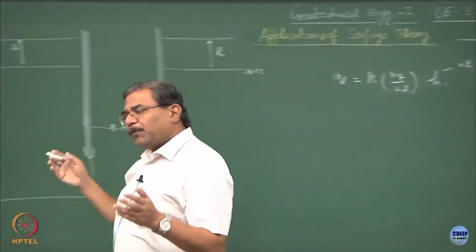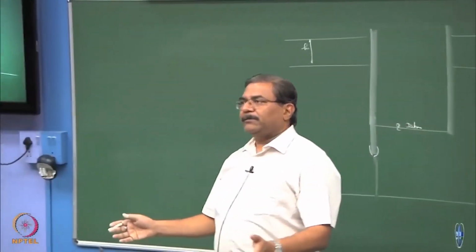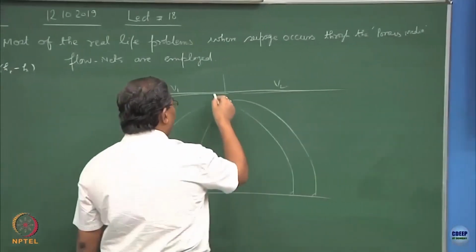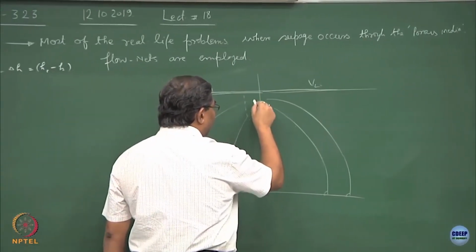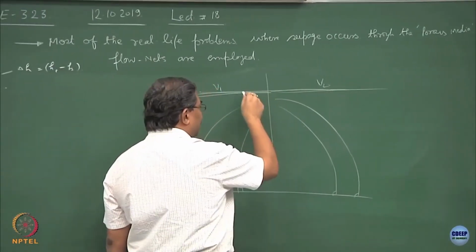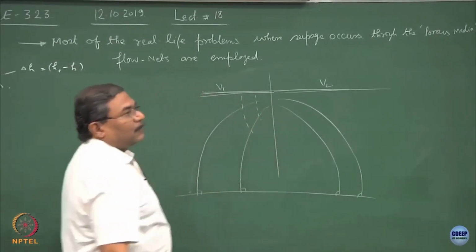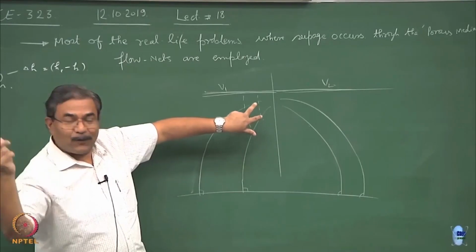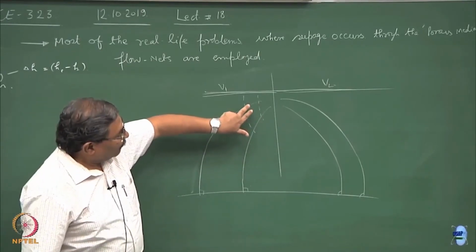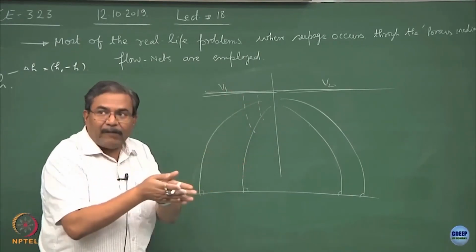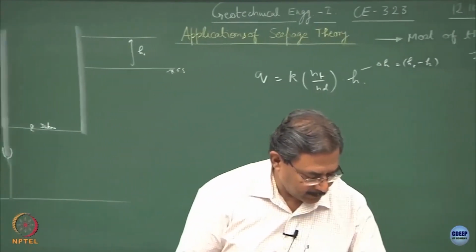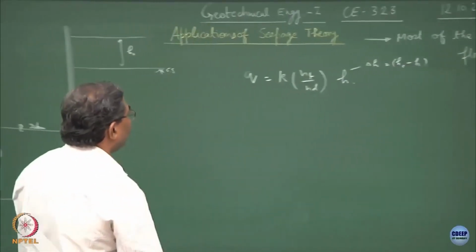Once the equipotential lines have been fixed, you start plotting flow lines, maintaining the geometry of squareness. It depends upon the step for the voltage which you have chosen, because your delta S is equal to delta N. So, if you are going for very fine, your flow lines will become very fine, with more number of channels.